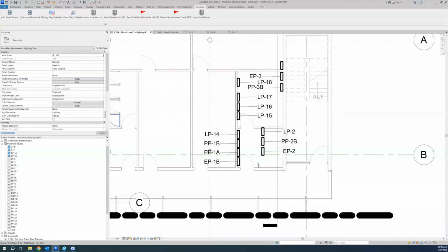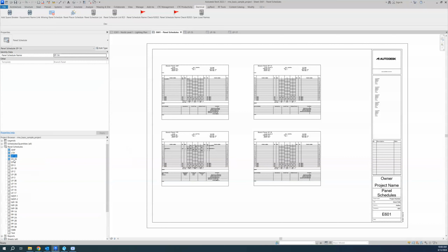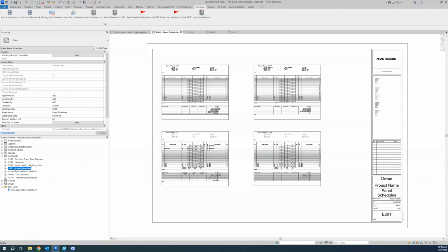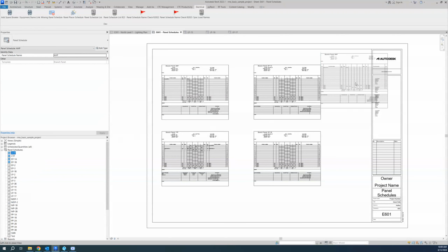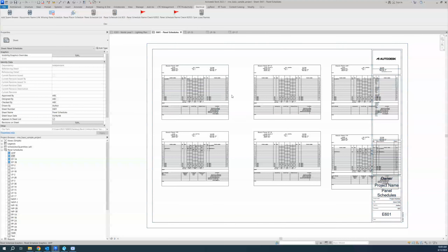The next tool is the panel schedule list tool. And this tool is also very big. I know Revit 2023 comes with this cool new function of saying if a view is on a sheet, which is pretty handy. But the thing is, it doesn't tell you if there's duplicates. So you might have maybe 20, 30, who knows how many panel schedule sheets with the size of these projects. But for the sake of demonstration, let me throw the same panel schedule on a sheet twice. I'm going to run the tool, and it's going to tell me